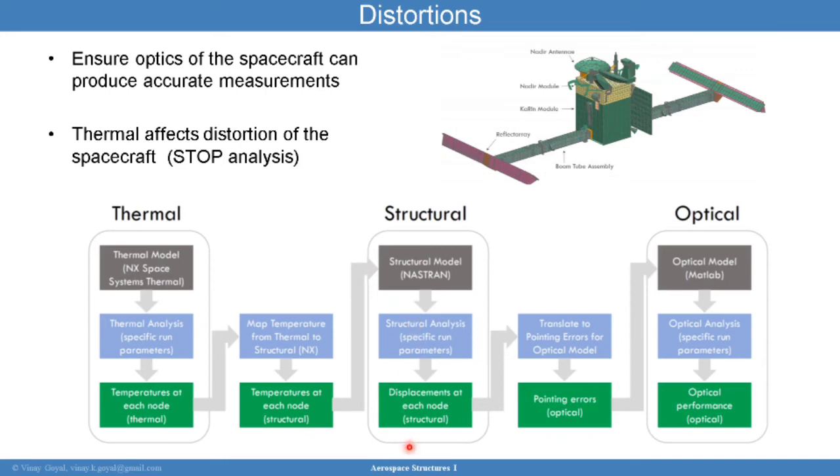You do a structural, thermal, and optical analysis. You start with the thermal analysis, analyzing the spacecraft as it is exposed to on-orbit environments, hot and cold. And that analysis, which is quite complex because it takes into account the radiation, heat effects, the cold effects, also has to model the orbits.